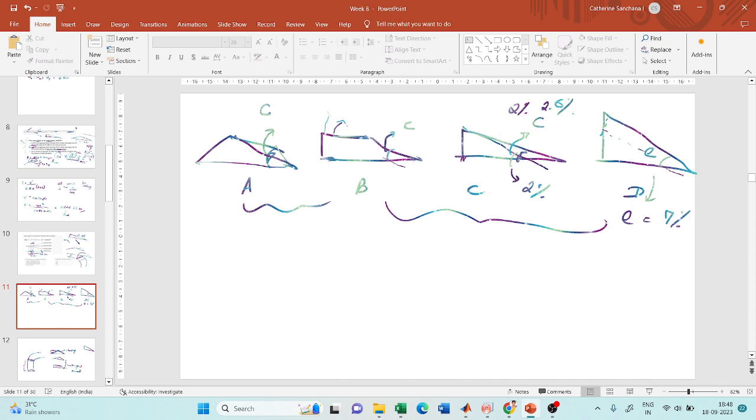So earlier it was here, it was just 2%. So I have to keep increasing this. Now it will become 7%. So till then you will provide a transition curve, because at the end of the transition curve your horizontal curve will start, right? So when your horizontal curve starts, your super elevation should be equal to what is required for the horizontal curve, right? So this entire B to D distance will be transition curve, and this is called as super elevation runoff.